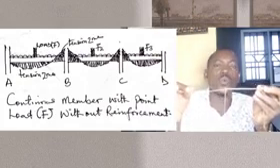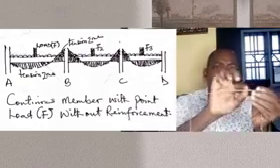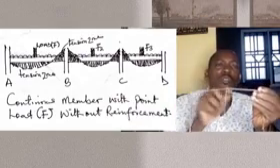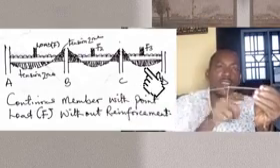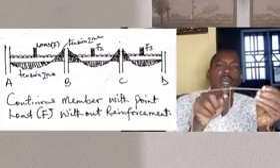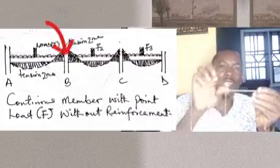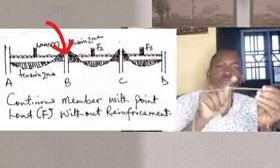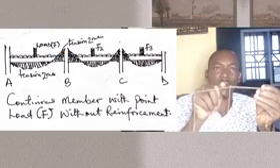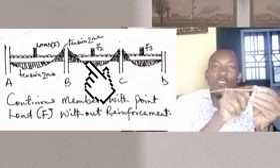All right, so when you have this kind of support condition, the moment you put load on top of this area and this area, and so on, the middle here tends to deflect. Likewise, this area tends to deflect. But something happens at this point: you start having hogging, something going up. This place will be passing through some tensile stress. At the bottom here you are going to have tensile stress, while here you are going to have compressive stress.